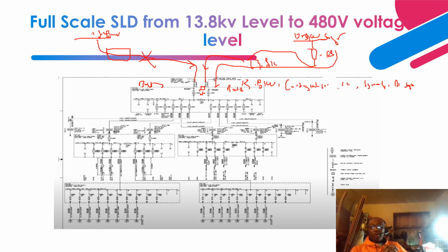That is more about the mechanical operation of the switchgear components, to be able to withstand it, and that usually happens during the first quarter cycle of the fault. There you have the asymmetrical fault contribution due to the X over R ratio, especially if you have rotating machines, such as motors, that contribute, or an emergency diesel generator that is running and contributes to the fault.